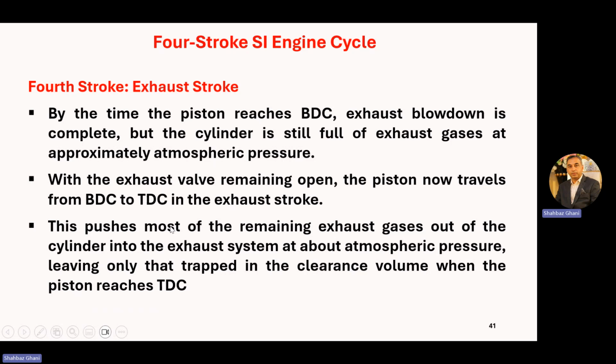This pushes most of the remaining exhaust gases out of the cylinder into the exhaust system at about atmospheric pressure, leaving only that trapped in the clearance volume when the piston reaches TDC. So most of the exhaust gases will leave the combustion chamber or the cylinder. Some of the exhaust gases will be trapped in the clearance volume, and they will remain there.